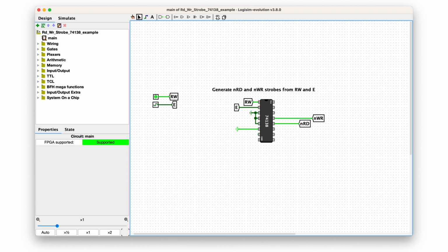Now first let's consider the output when the E clock input is low, which will be the case when the RW signal transitions to the value that will be used for the bus transaction. The input value is a 0 if RW is low for a write and 1 if RW is high for a read. That means Y2 and Y3 remain high or deasserted, and since nothing is connected to the Y0 or Y1 outputs, nothing happens.